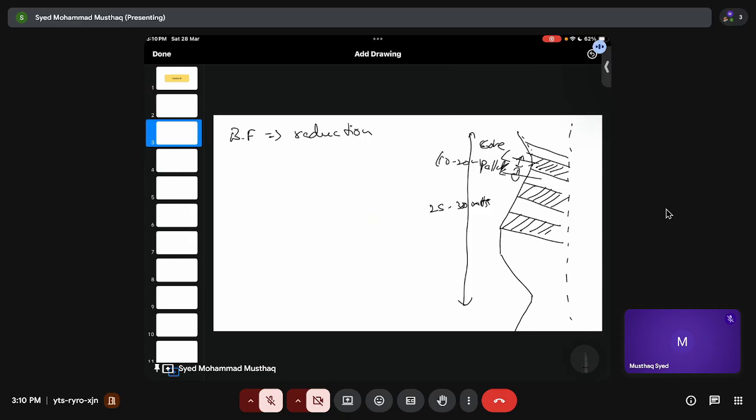Pellets are more, see again I will explain the difference. What is the difference between pellets and sinters and briquettes? Okay, so pellets are mostly more regular, or you can say more technically engineered when compared to your sinter. So a pellet has a defined shape like circular or spherical, and consists of your ore, flux, coke, and some binders to hold these things together.